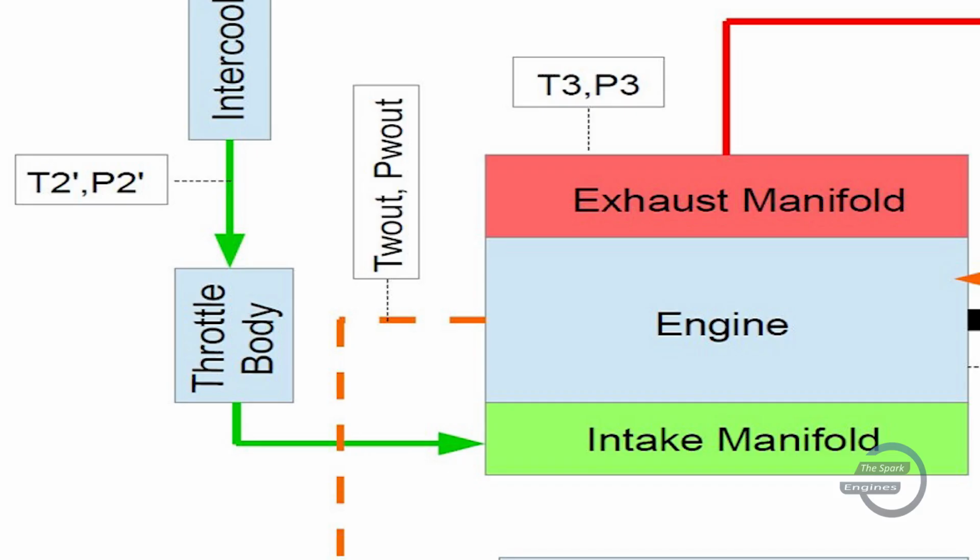Hence, with the help of that sensor, the ECU will understand the properties of air within the intake manifold, and by using the throttle body opening percentage at that instant, the ECU calculates the amount of airflow, in case an HFM sensor is not installed in your engine.